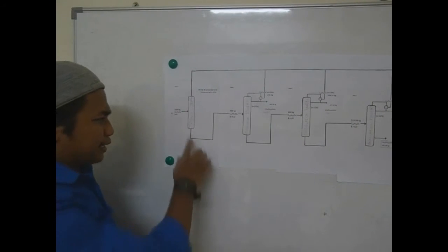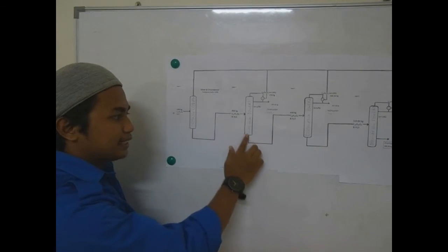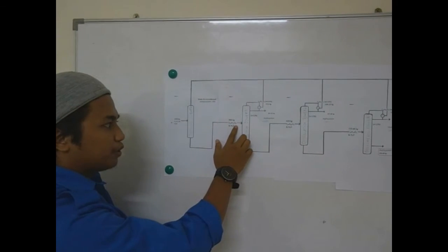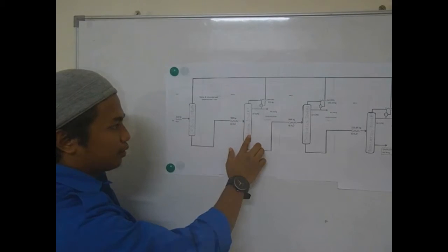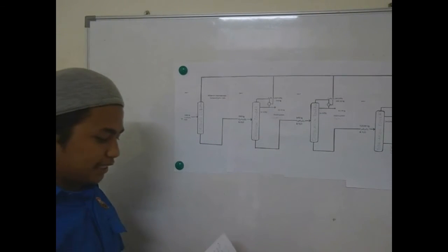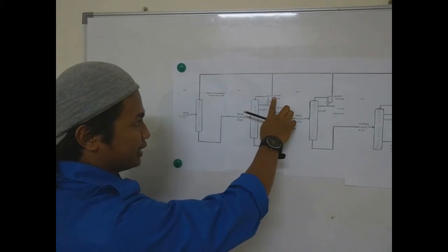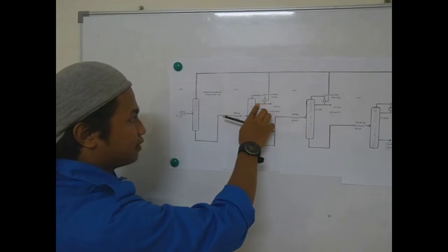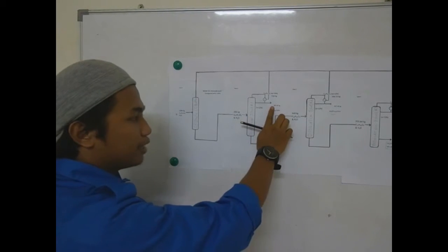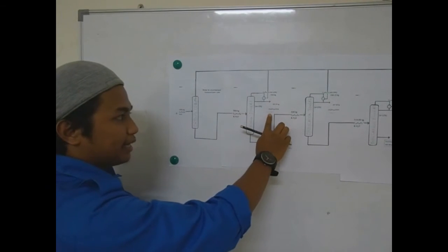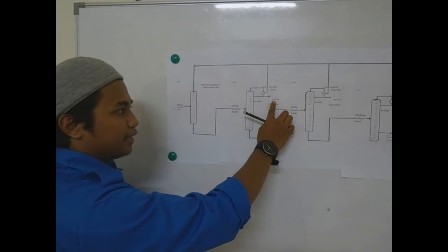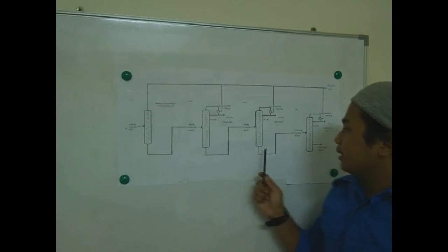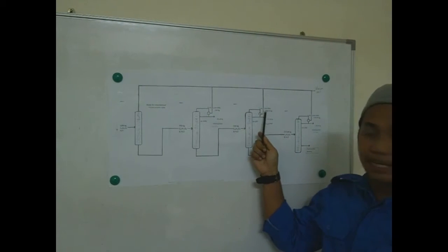Okay, next, the pure triglyceride plus water will enter distillation tower 1, which is 900 kg of pure triglyceride plus H2O. For distillation tower 1, the composition of undistilled product is 24%, which enters the vacuum unit, and 12% will be recovered back into the distillation tower. Okay, the first product we have is caprylic acid, which is 601.92 kg.